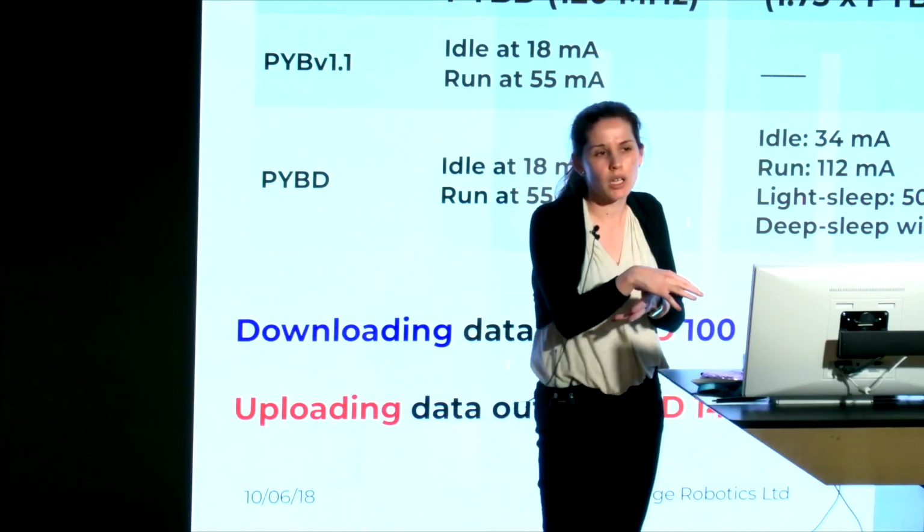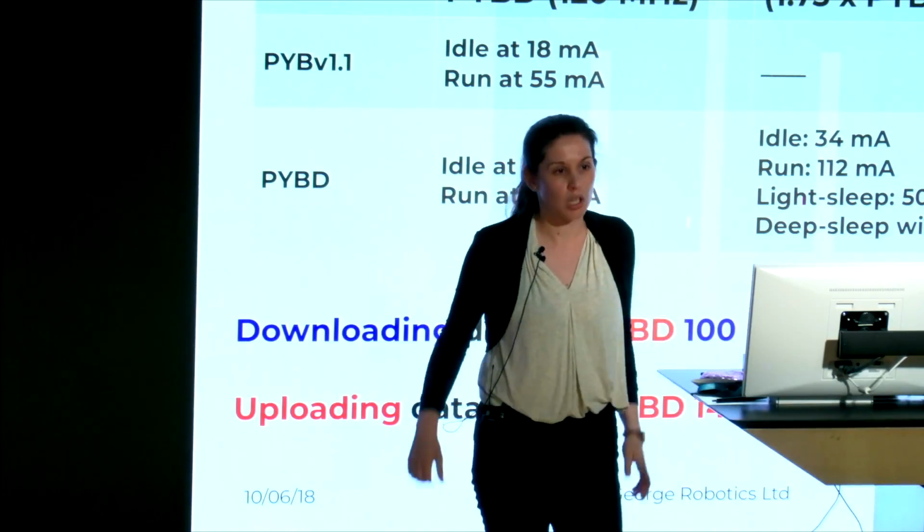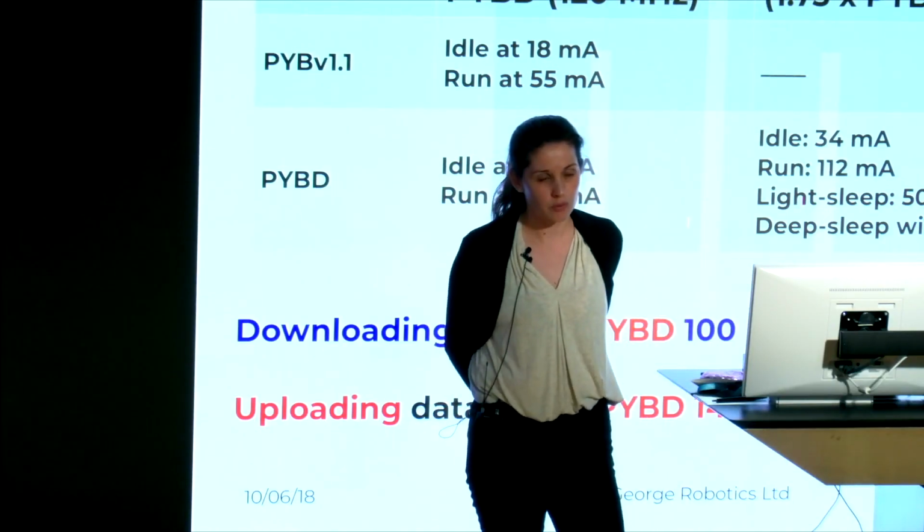Well, how does MicroPython work? Which operating system do you use, or is it an operating system as well? Well, it's a kind of operating system for your microcontroller. But you don't really need an RTOS or anything in between on your microcontroller, so you just need to flash the firmware on the microcontroller? Or do you mean the PC where you interact with your device, like how I plugged it in and showed you? Just the microcontroller. So MicroPython is all you need on the microcontroller. Yes, there's no RTOS or other layer in between, so you can flash it right on it.